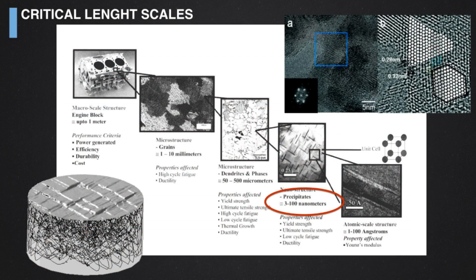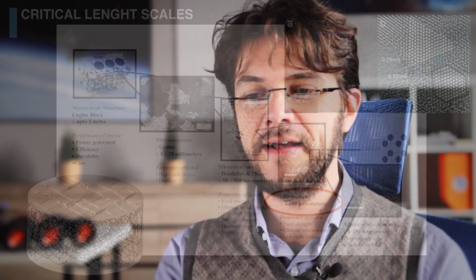Let's go to the precipitates and to nanoscale phenomena. On the left side, you see what happens when you submit a material to a plastic deformation for a long time. This is the so-called dislocation forest. Dislocations are nanoscopic or nanometric defects in the ordering of the atoms. You may think about a roof which has tiles. If the tiles are perfectly aligned, there is no flaw in it.